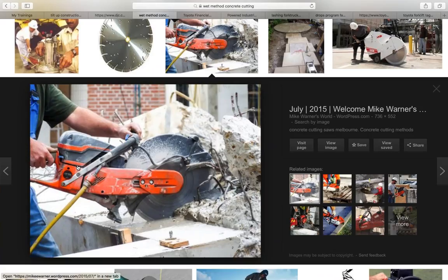And then in addition to that, wash frequently, right, with lanolin-based soaps or using lotion. That way, keep your skin from getting ashy or dried out, and control some of that dust as well. Bathing after each shift, of course, and then PPE. Traditional PPE that we use: hard hats, safety glasses, face shields, respiratory protection, gloves, knee pads, toe boards, safety boots, all of it, right?